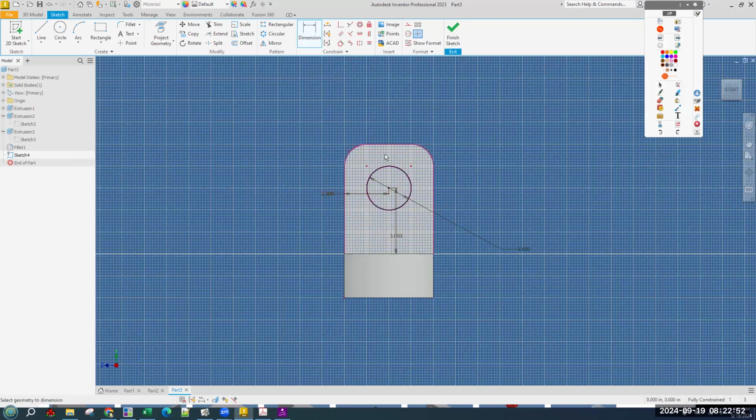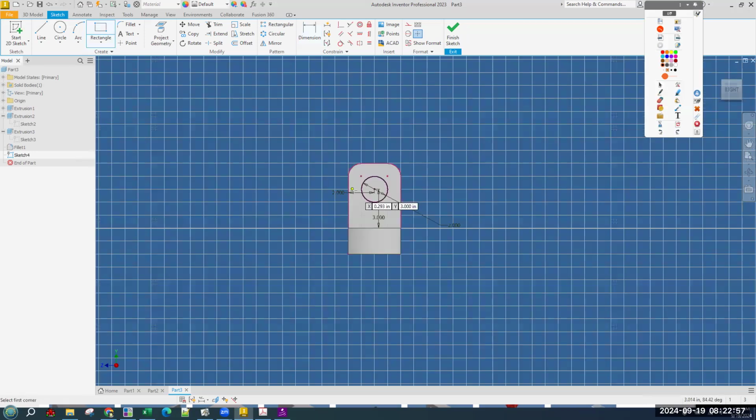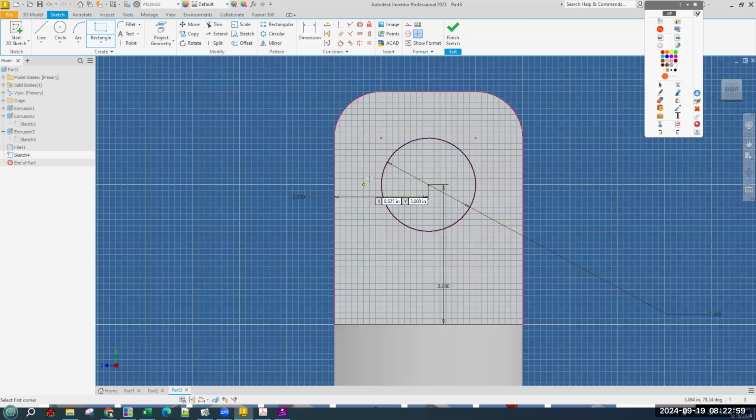We can just do this all in the same move. We could cut extrude that, make another sketch, and so on. But I think it's easier to just get a rectangle tool, and you'll get another soft snap due west of the center point, at exactly 3 o'clock, 6 o'clock, 9 o'clock. So that's 1.